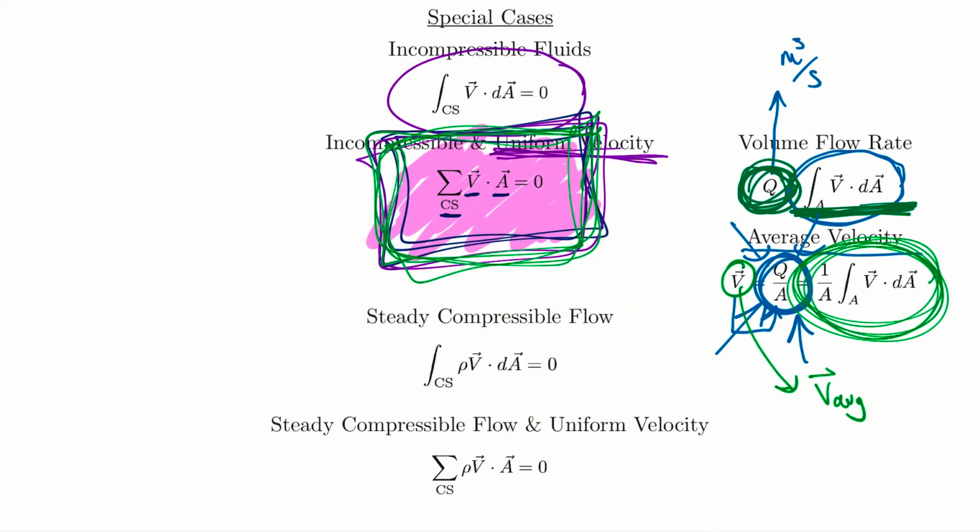Now, we can't forget about compressible flow, of course, just for completeness, the following two equations down here. So in compressible flow, one way we can simplify it is by saying we have steady compressible flow, because that's something we'll commonly have. And if we have steady compressible flow, and the first term in that expression was the d by dt expression, right? So for steady, we only keep the second term, so we'll end up with this expression here, which is a little easier.